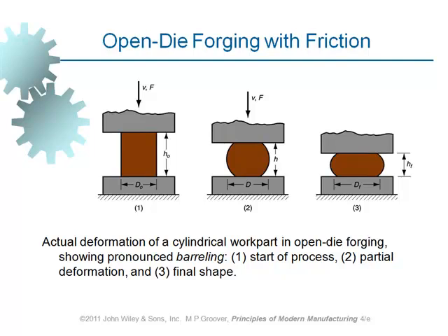Not just that, if forging is taking place at elevated temperature, then there is heat transfer up here, which is more than the heat transfer which takes place in here, meaning that the temperature of the material in the middle will be greater than the temperature of the material up there. When material has got a higher temperature here, deformation in here is easier than the other two ends. So there is more deformation taking place in the middle compared to two ends. Because it's colder on the top and at the bottom. In the middle, it's hotter.